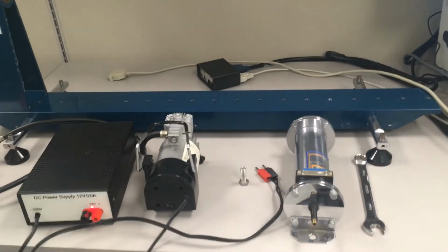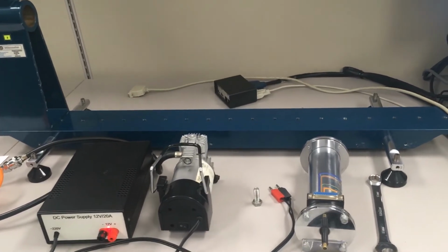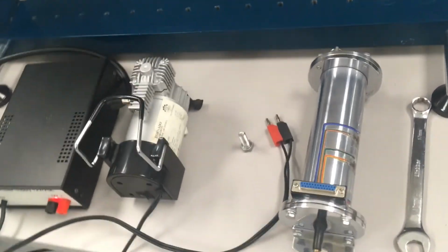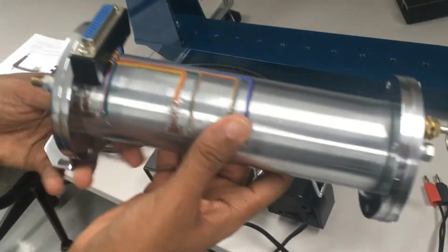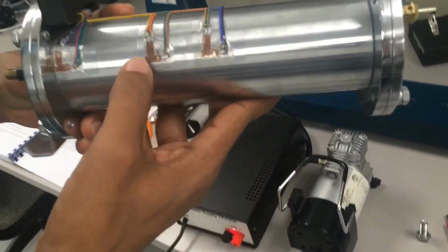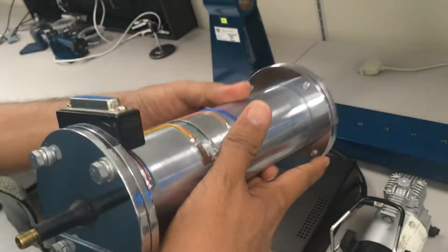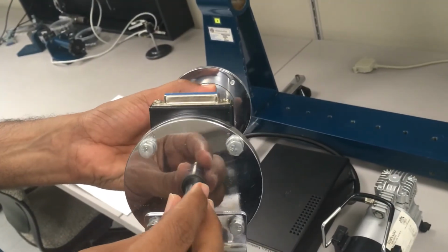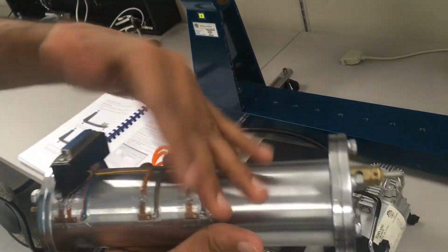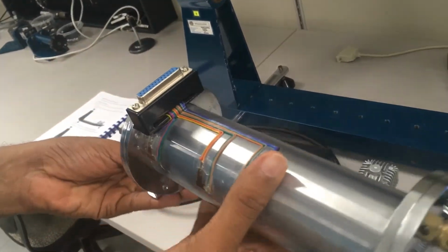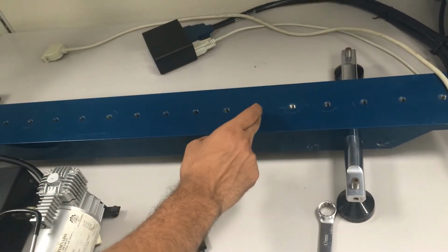Good. So if we want to assemble the experiment, step number 1, install specimen number 10 for loading of pipe into the mounting hole 8. So this is specimen number 10. This is a cylinder. We have multiple sensors, 1, 2, 3, 4, and basically what we are doing, we will fill this cylinder with air, and at the end we will measure the stresses, hoop stresses around the surface of the cylinder. So this is specimen number 10 in hole number 8. So 1, 2, 3, 4, 5, 6, 7, and 8.